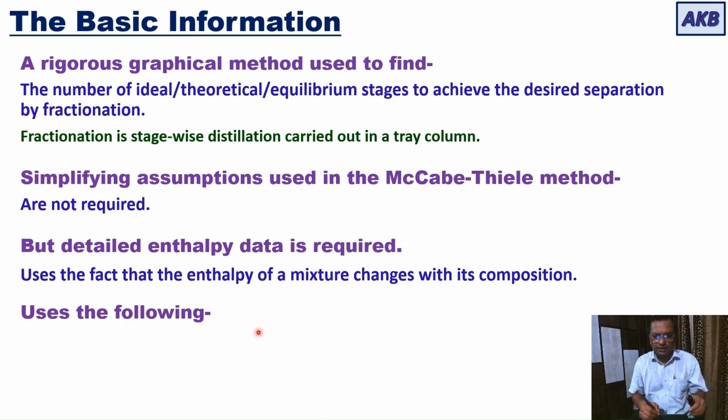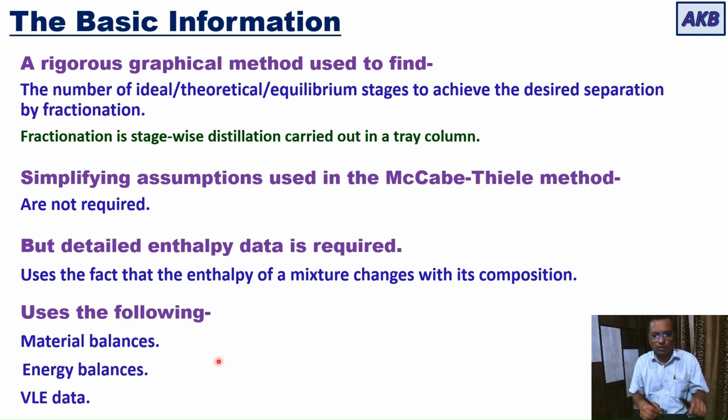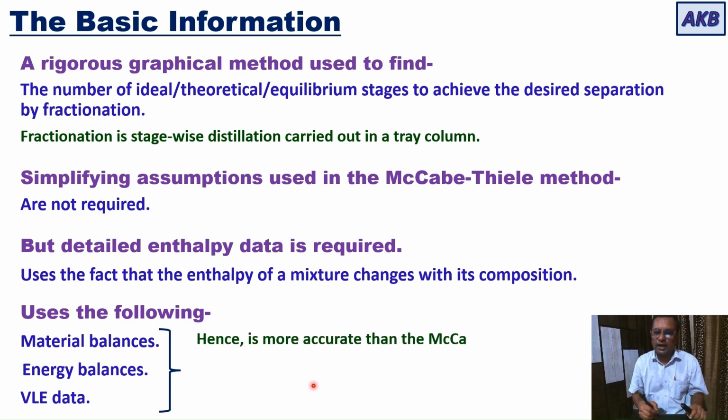What does it use? It uses the following things. It uses material balances, it uses energy balances, and it also uses VLE data. Material balances are used in this method, energy balances are used in this method, and even the VLE data, vapor liquid equilibrium data, is also used in this method. And that's why this method is more accurate than the McCabe-Thiele method.